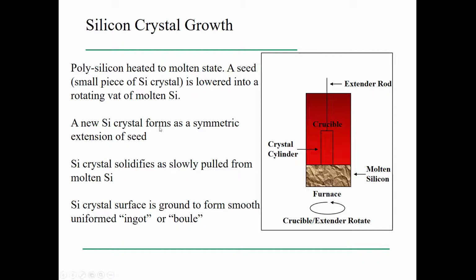Once that ingot is formed, it is sliced into the wafers, where the integrated circuits are then created. If you grow an N-type crystal structure, a small amount of phosphorus dopants would be introduced to this melt. If you want to grow a P-type crystal structure, a small amount of boron would be added to this melt.